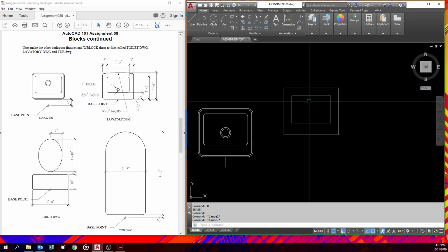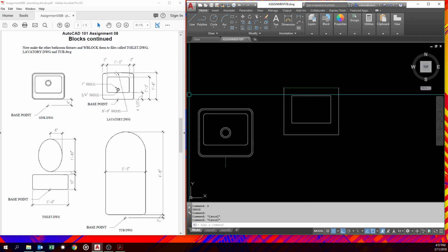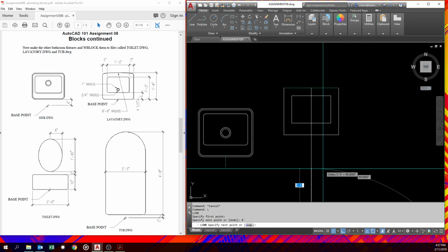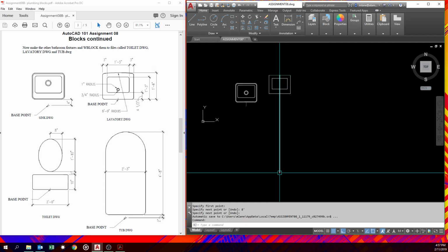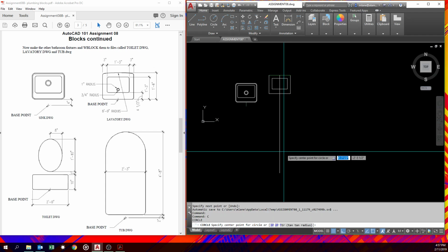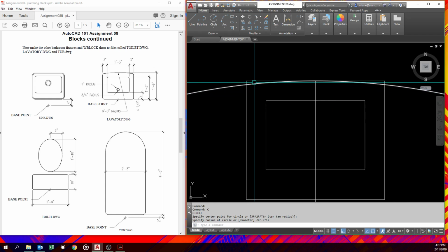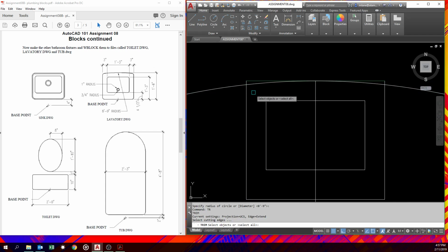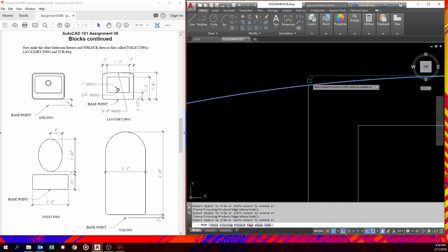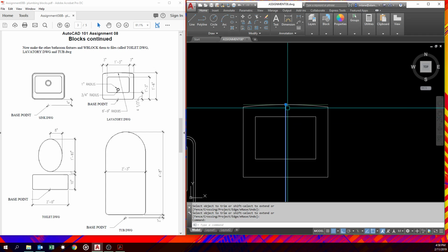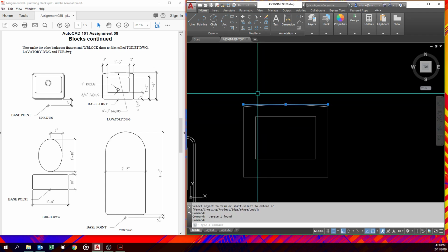And so the easiest thing to do, I mean, there's a couple. We use the arc command. You can do circle a number of different ways, but let's start with that part since we're talking about it. Let's draw a line down 8 feet. That is the center of that arc. So let's just draw a circle that's 8 feet. Well, at this point, we can just hit trim. Aha! So trim, pick our objects, get rid of the bits we don't want. Yay, joys and yellings. Delete this. Could probably delete this at this point.